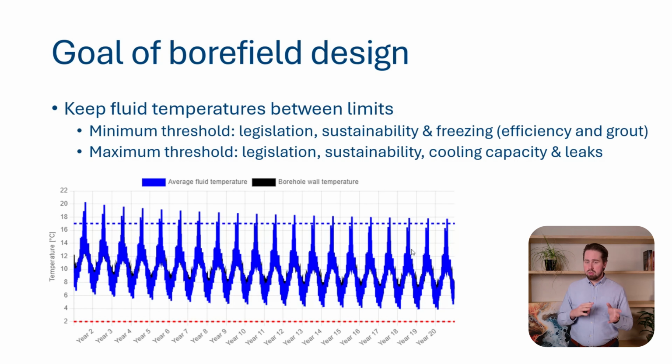And the last problem is with leaks. So plastic, it becomes longer or it stretches with temperature. There is a temperature variation there. So if you have quite long horizontal connections and your temperature fluctuates quite a lot, then your pipes stretch and they shrink again, and this can cause leaks in the welds over time.